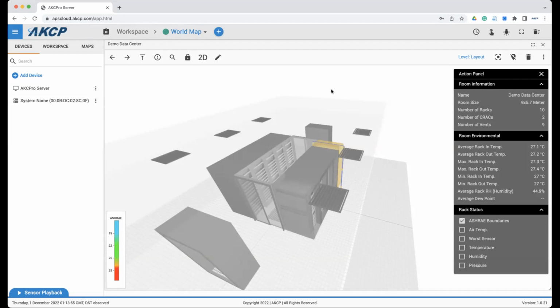Right, yeah. So if you use the sensor data, that's what you have now. If you do what Gabriel did, which is manually input values, then you could use that as a projection. So you would say, okay, this is what my data center is now. I want to add two servers to this rack. The manufacturer's stated power consumption of these servers is 1 amp each. My rack's currently using 4 amps, so you would input 5 and then run the simulation on that.